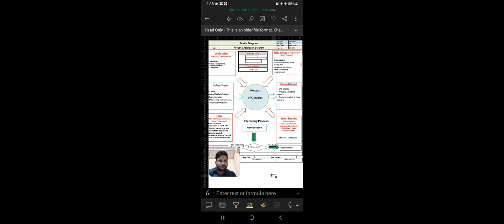And in the input section, with what means what materials or equipment are used, that is measuring devices, equipment, parts, material, computers. And how we can measure the SPC, meaning the methods, procedures and techniques: data collection, calculation of X and R charts, calculating the control limits, calculating Cp and Cpk.